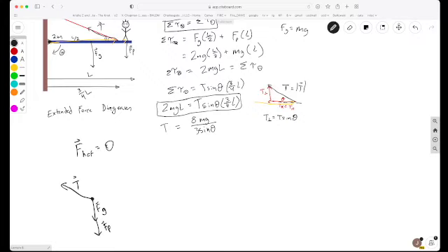So clearly we need another force, because these can't add to 0, right? They don't add to 0. We do have some up component from the tension and some down component from the other two. So maybe in the y direction that could work. However, in the x direction, we have this negative x component from the tension, right? We have this piece of the tension, but there's nothing left to balance it out in the positive x direction. So we need another force.